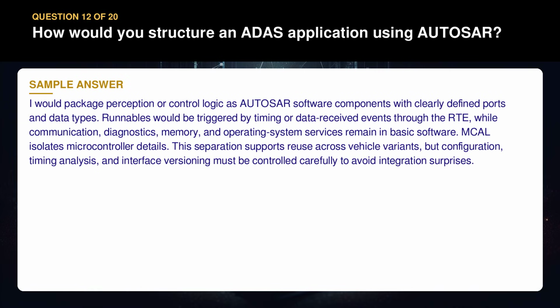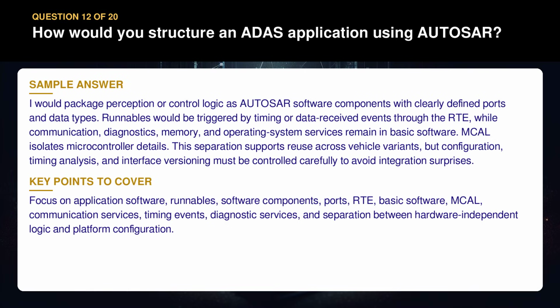MCAL isolates microcontroller details. This separation supports reuse across vehicle variants, but configuration, timing analysis, and interface versioning must be controlled carefully to avoid integration surprises. Focus on application software, runnables, software components, ports, RTE, basic software, MCAL, communication services, timing events, diagnostic services, and separation between hardware-independent logic and platform configuration.